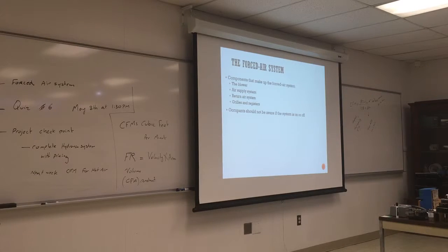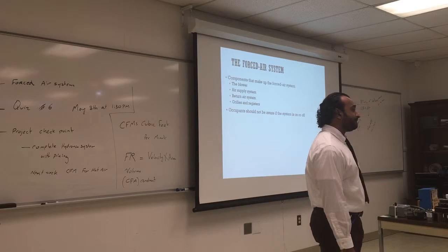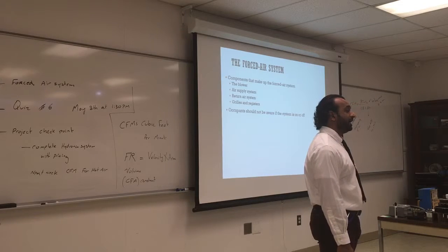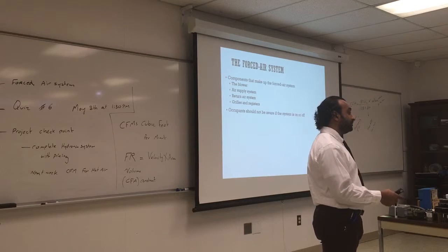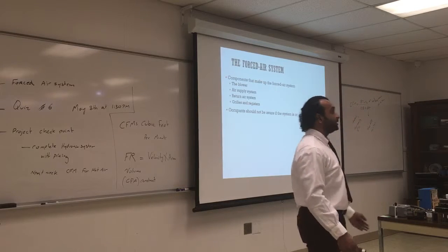If you're doing a new install on the house though, would you put two returns in, one in the floor and one in the ceiling? Ideally, yes, but it's not always the case. It becomes a struggle when you have the cold air coming from the bottom. It's going to take a while to build up enough cold air, so it takes longer.